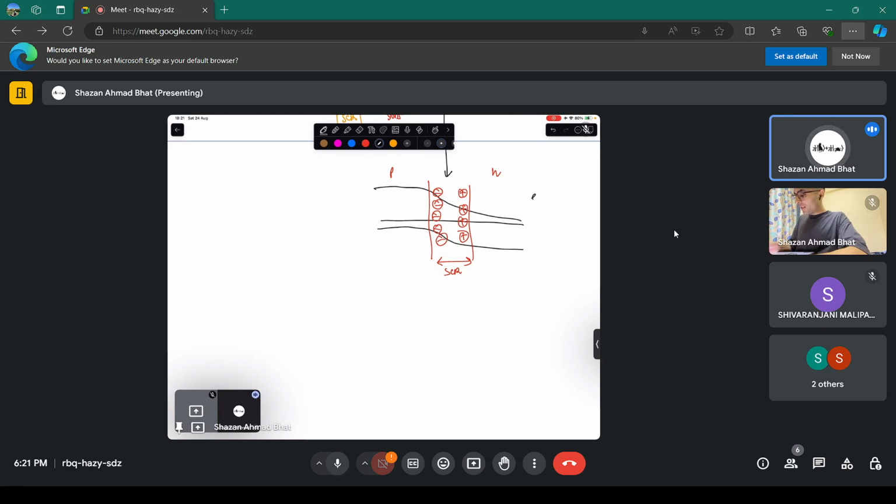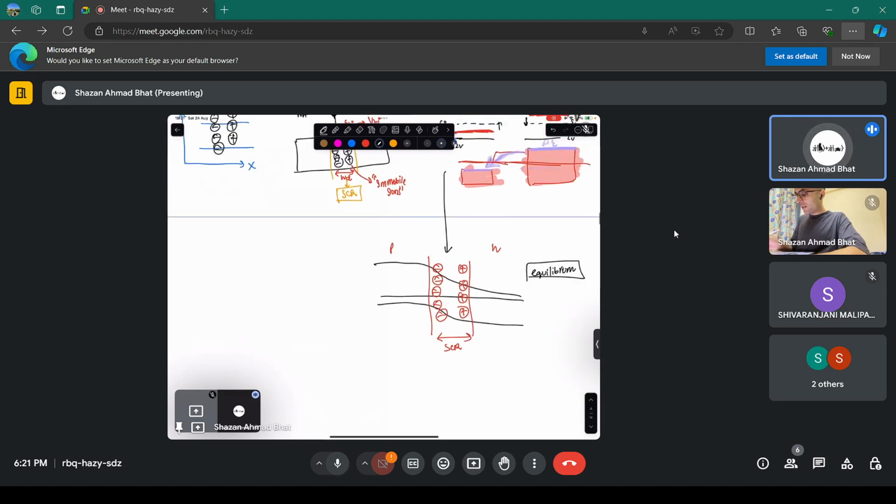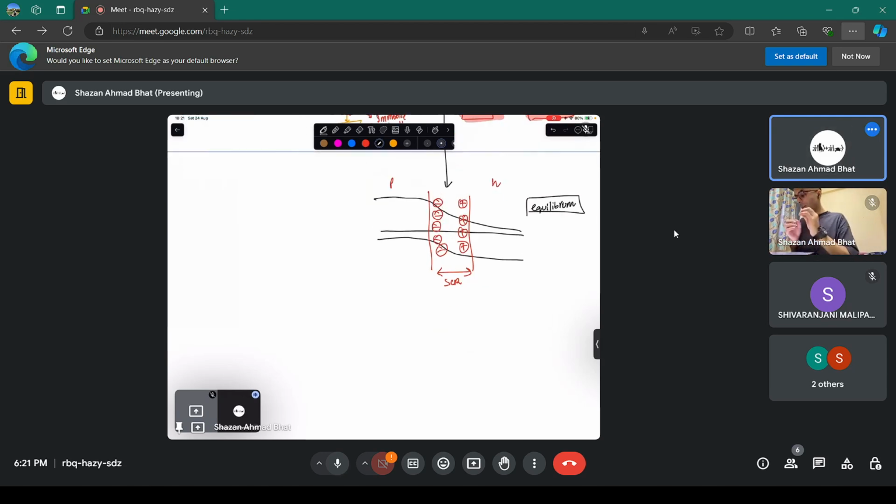Now, this is an equilibrium. This means you have connected these two semiconducting materials, and the moment you connected, the equilibrium is set up. It happens instantaneously when a diode is fabricated, and the space charge region gets formed, and then there is only very minimal movement of electrons from the n side to the p side, and holes from the p side to the n side. Because of the electric field developed, it hampers the motion of those charges, and it acts like a barrier here.